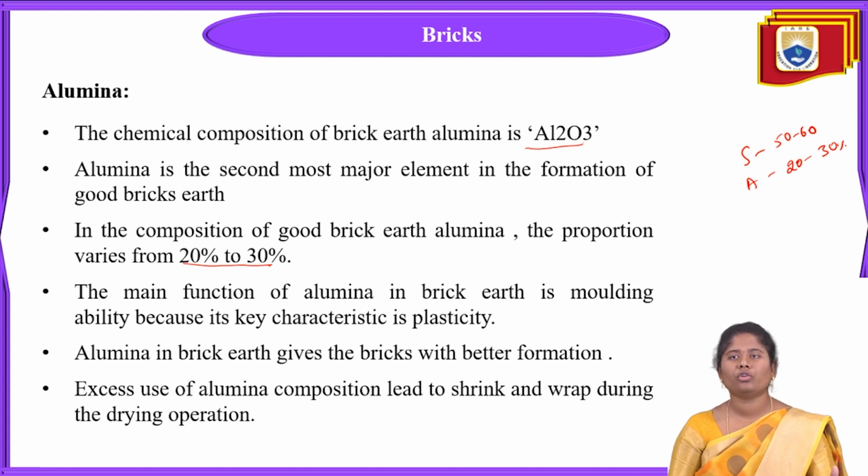When we dry these bricks, if the alumina amount is in excess, about above 30%, it leads to shrinkage and also warping when it is in drying condition.